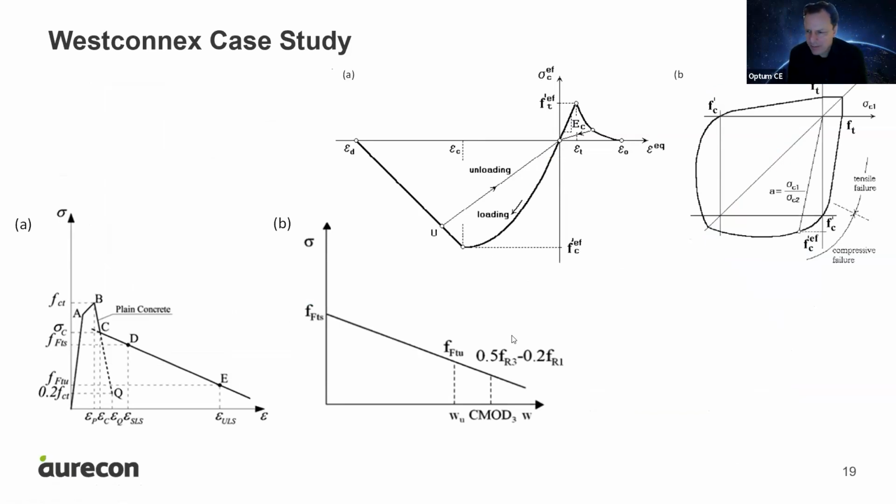David, the amount of fibers, you settled on some fiber count. Yeah, absolutely. For this thin shotcrete lining with the high performance fiber, some people will be surprised because they might be thinking of high numbers like 50 kilos per cubic meter. Now we use only 35 kilos of fibers per cubic meter, and for the segments, we're using only 31 kilos of fibers per cubic meter. So it's quite small numbers.